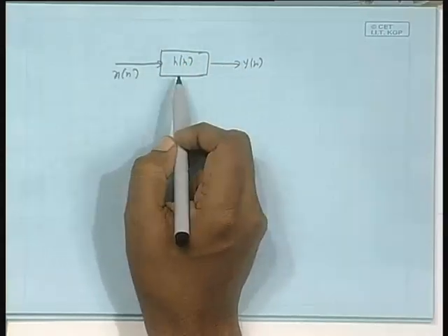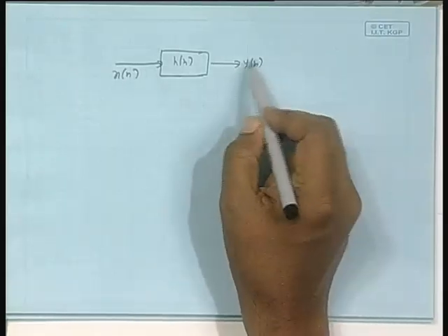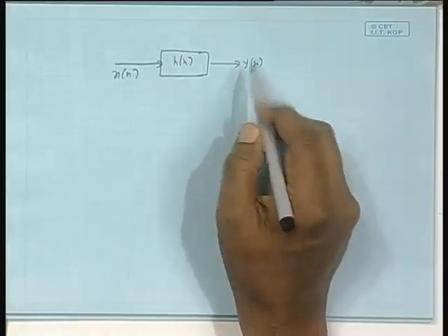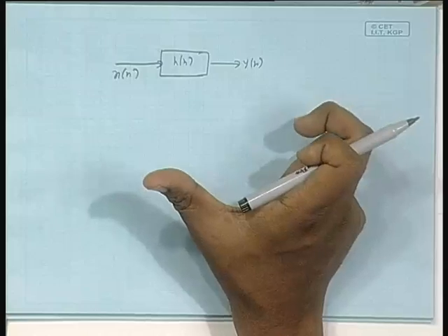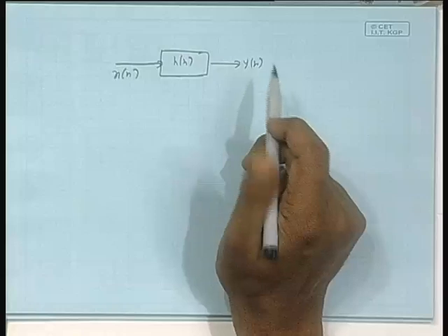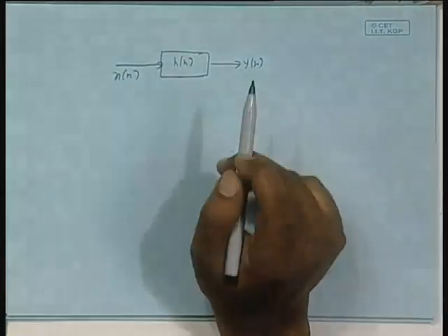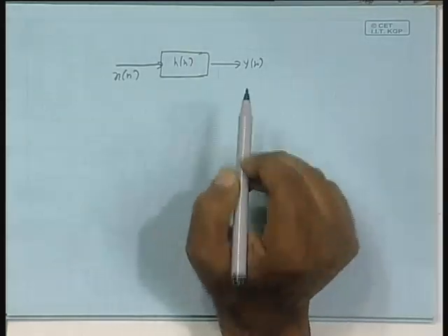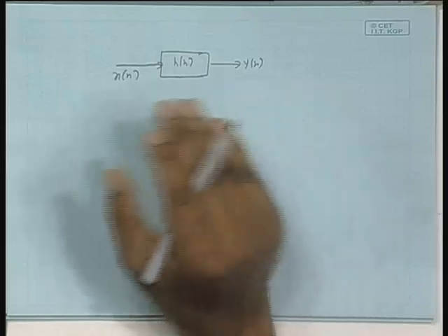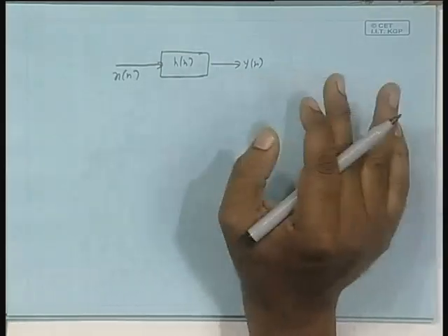So, I take the N point DFT, multiply the two DFTs, and that will again be a sample of the DTFT of this. But if I take the inverse DFT of those samples, I do not get y n, because y n is a longer sequence; its length is not capital N, it is 2N minus 1, from 0 to 2N minus 2. Then the question was, even if I persist with this, that I will do X k into H k and take the IDFT, what do I get for y n? I get an N point sequence, but what is it? How much of it comes out to be linear convolution, and how much is the error? So, we worked it out.